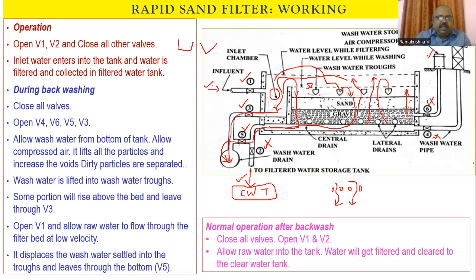So these are 3 stages. Usually the filters will be cleaned once in every 24 hours or 48 hours. But normal practice is they will be cleaned every 24 hours. The entire cleaning operation takes around 30 minutes.